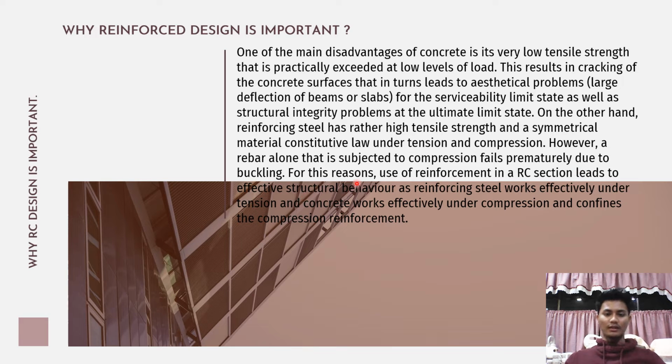For this reason, use of reinforcement in reinforced concrete section leads to effective structural behavior as reinforcing steel works effectively under tension and concrete works effectively under compression and confines the compression reinforcement.